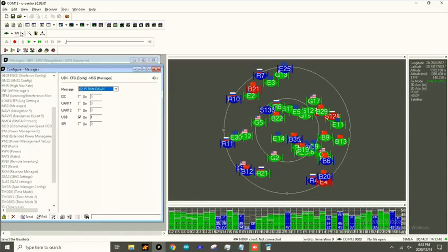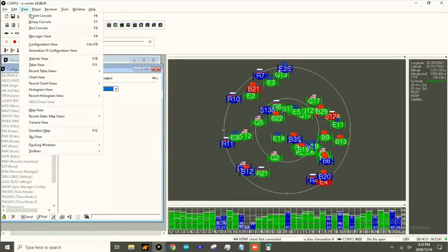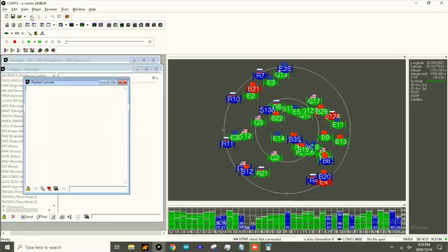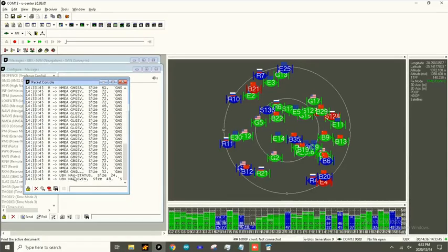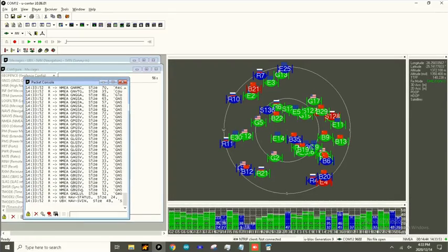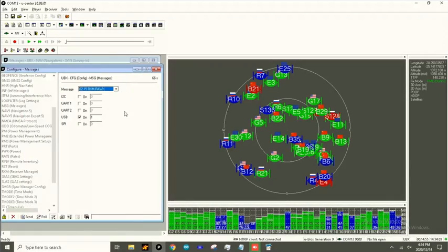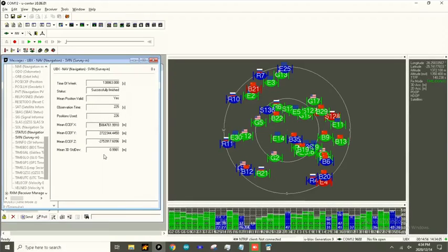To check these messages, we can once again go to our packet console under the View tab. And we should see the RAWX message or flag here and there in the output. There we see it, just so briefly. So that's all. We have the NMEA messages, we have the u-blox raw messages enabled as well. I'm going to close this window, and now we want to record this data stream for post-processing.